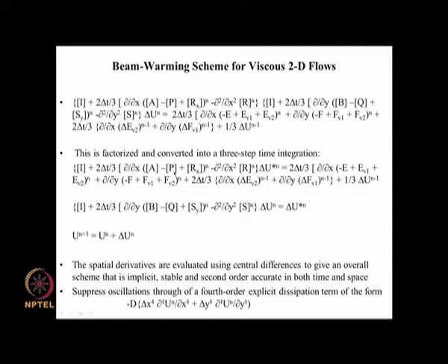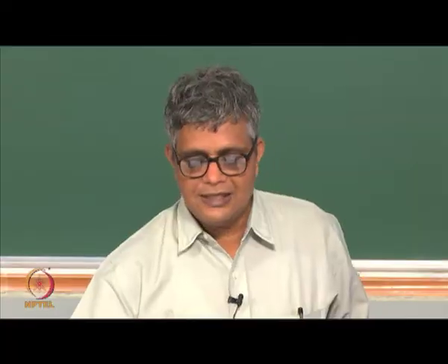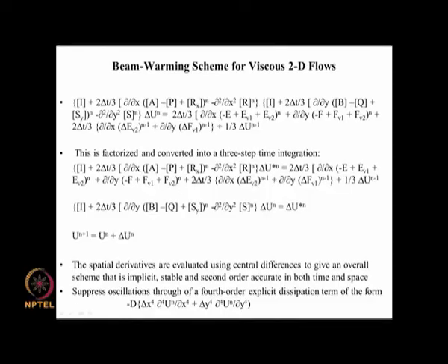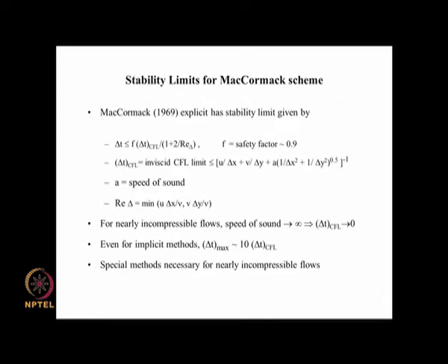That is possible only for small values of delta t, not very large values. So, when you take too large a time step, you have problems that can arise because of this lagging of the coupling and nonlinearity terms, and that can limit the delta t values that you can take. Okay.